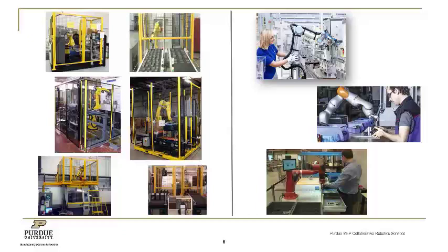When we do those in-person demonstrations of cobots, I have a segment I like to call "Get Hit by a Cobot," where I invite the participants to get up and take turns standing in the path of the cobot as the arm is moving back and forth, and feel for themselves what the sensation is of getting hit by the cobot. People invariably are very amazed at how fast the robot responds and how quickly it stops, and so it's really an eye-opening experience for them. And it really drives home why cobots are safe to work around people.